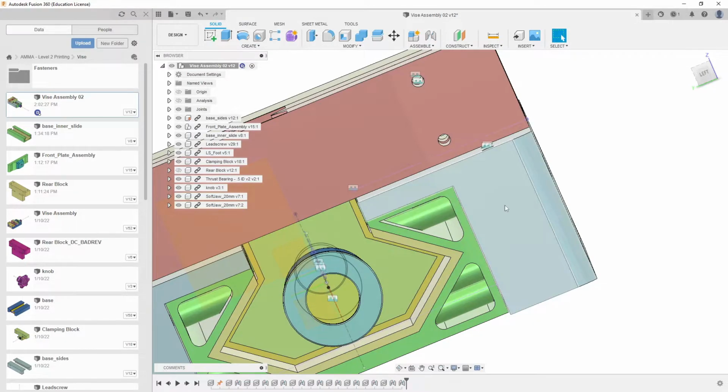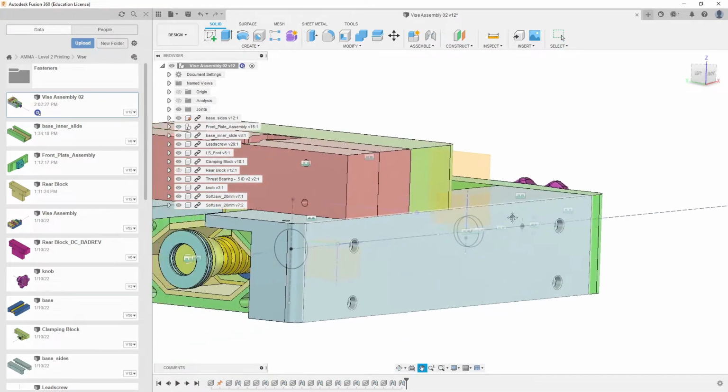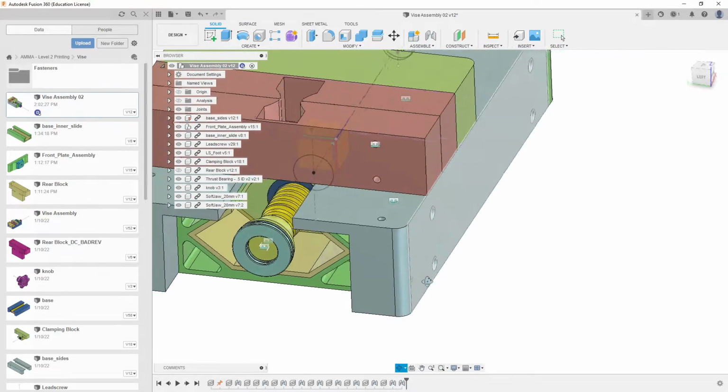So if I were to look at a cross-section, say right here, in this particular case, I have it counterbored maybe more than I need it to be, so that the fastener will stick through and a good portion of it will go into here. And that is also based upon the actual fasteners that you have or that you can get a hold of, you see? So that has to work.